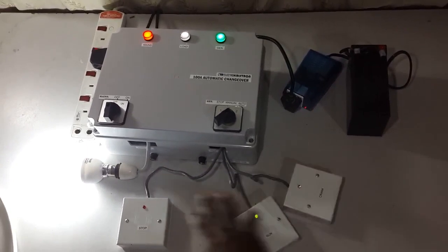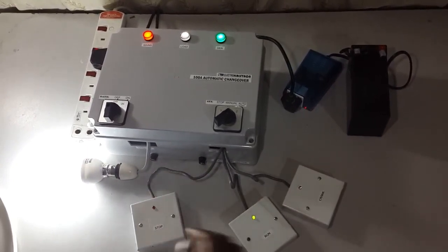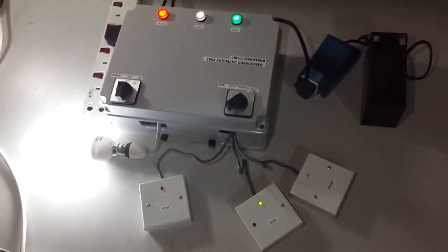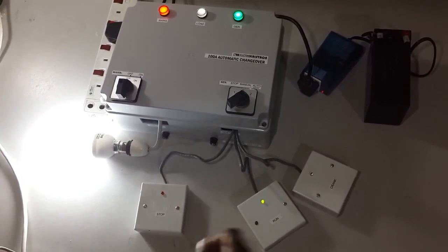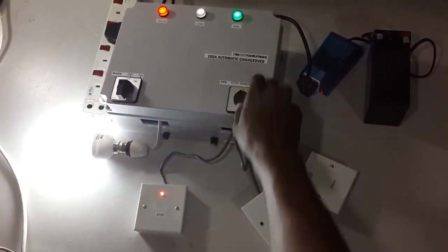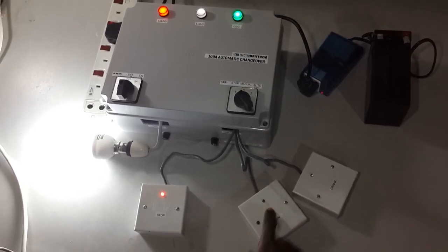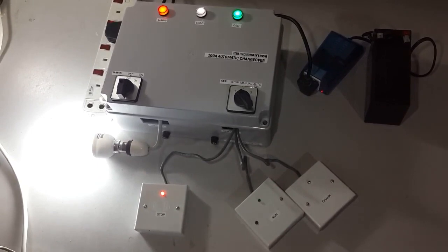And for such generators, only the stop control line will be needful, to be connected to such a generator. Only the stop control line will be needful. Okay, we won't be concerned about the run and the crank. All we need is just the stop control, and then of course the gen will stop.